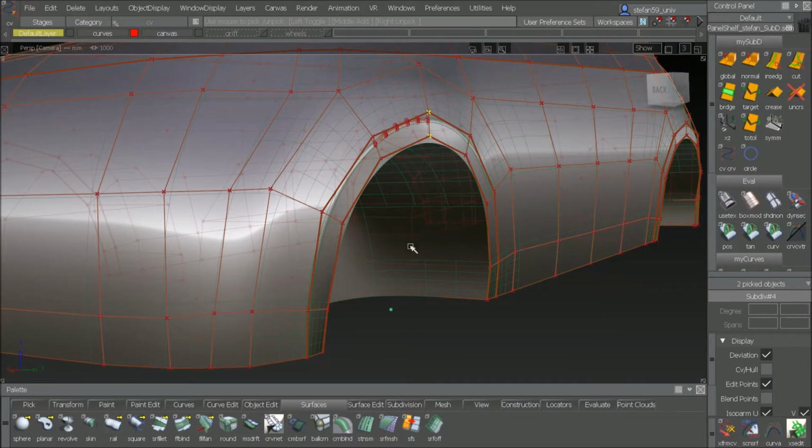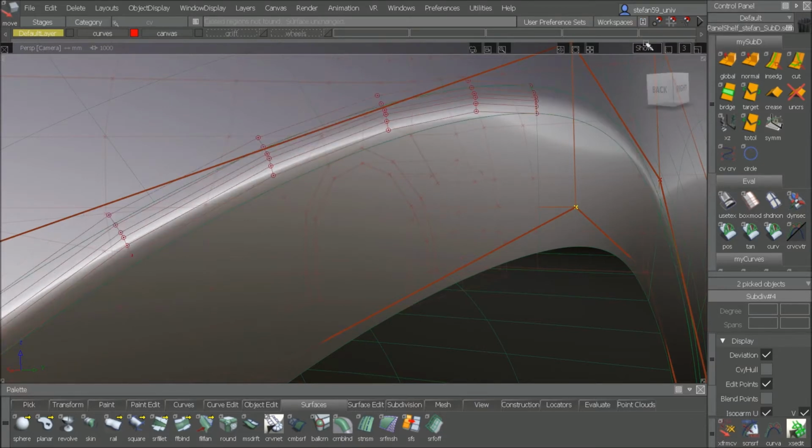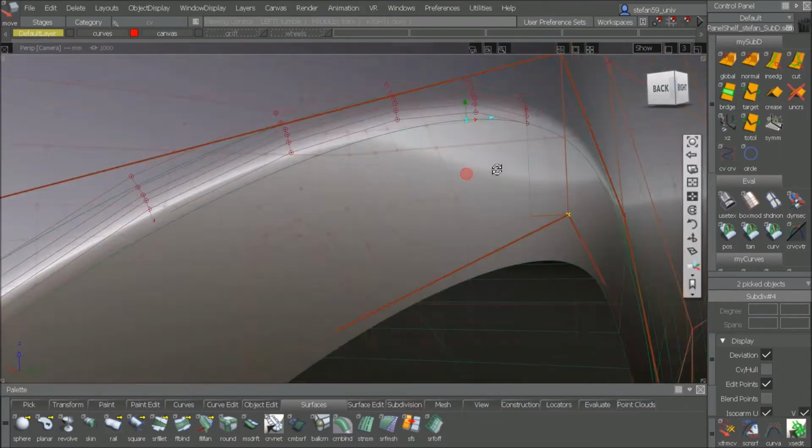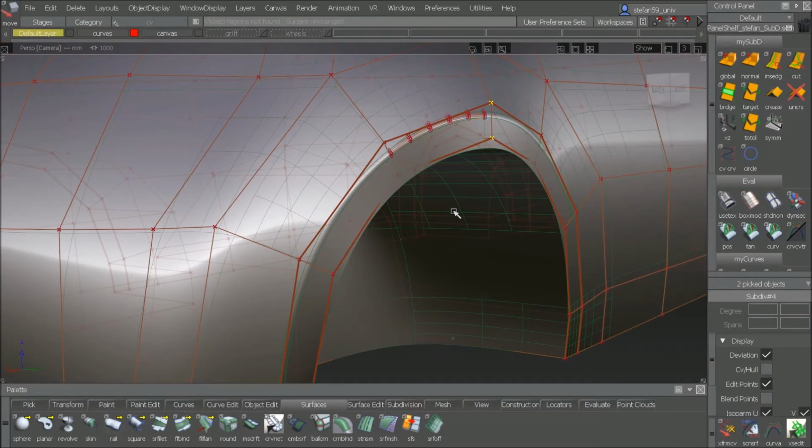So I take those two, let's say, and move them in Y direction. So I can quickly change it. Now the fillet doesn't come updated because I suspended update. So now I resume, and the fillet is recalculated by history. Now it's fitting again. So that's the trick. I do an undo, and it goes back, of course, because it updates again.